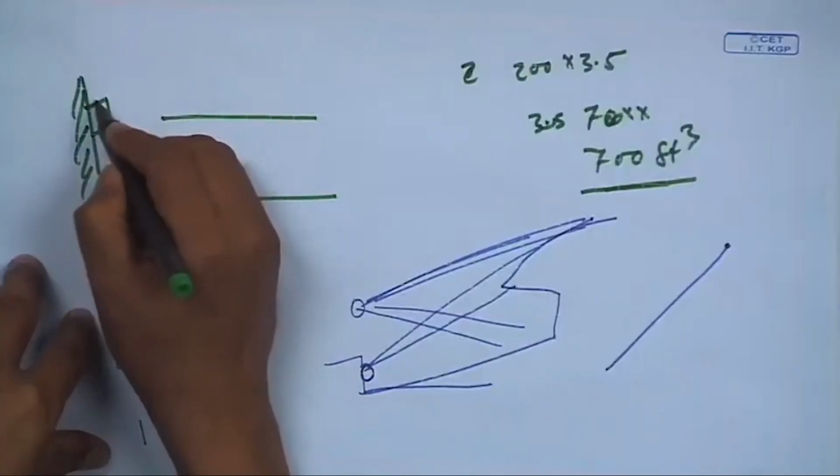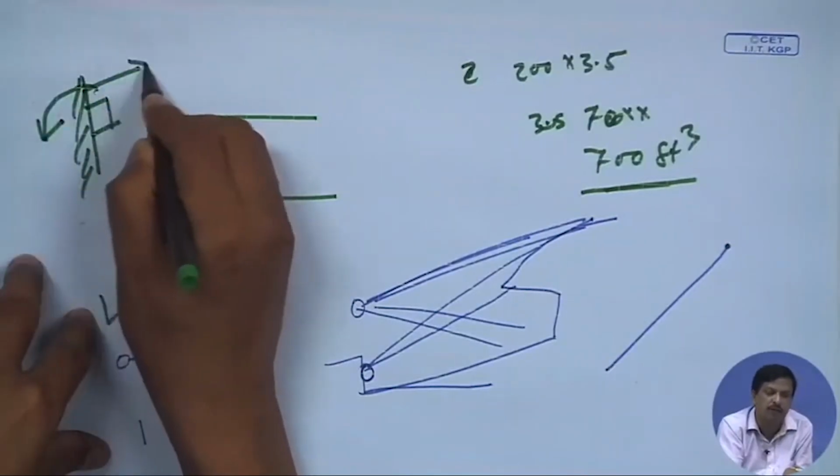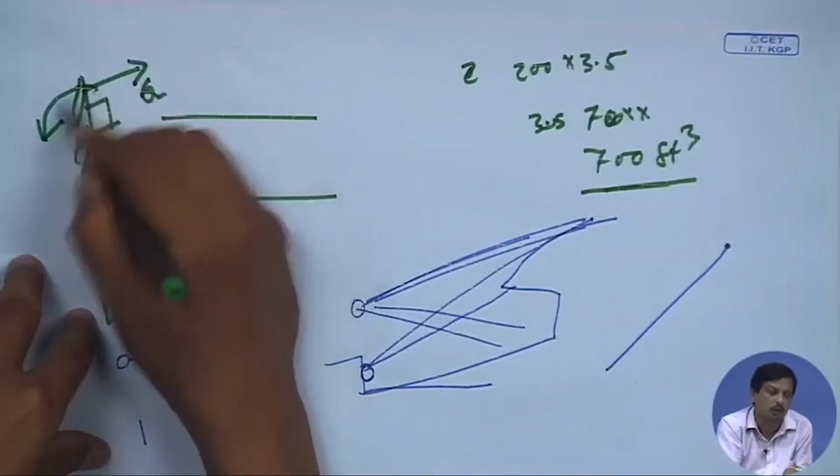Okay. So, if I put an acoustic blanket at the backside and then put a sound source, what will happen? Let us say the blanket is 100% absorptive. If I put a sound source here, the sound which is supposed to go this side and be reflected back to increase the directivity will be absorbed.